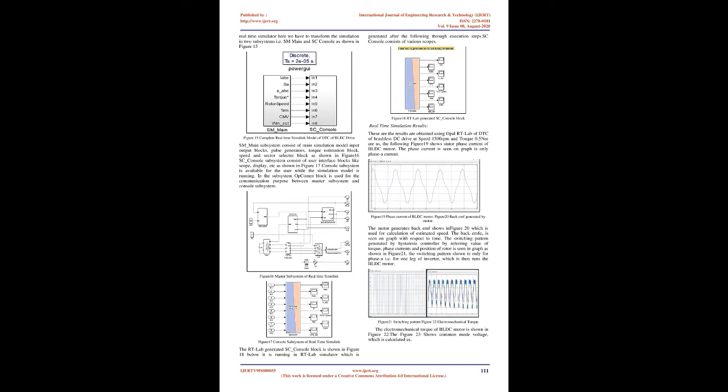C. Real-time implementation for direct torque control of BLDC motor drive. 1 software synchronization. The MATLAB simulation diagram for DTC of BLDC motor drive is shown in figure 15. To run this simulation model in the real-time simulator, we have to transform the simulation into two subsystems, i.e. SM_main and SC_console, as shown in figure 15. Figure 15: complete real-time Simulink model of DTC of BLDC drive.